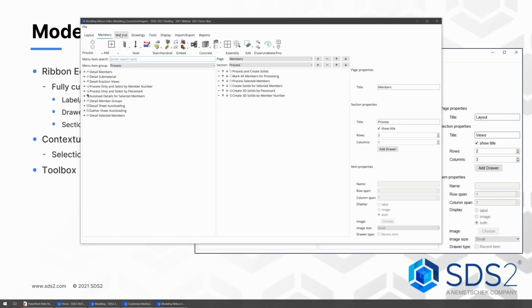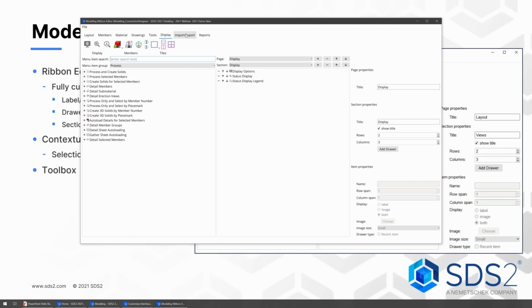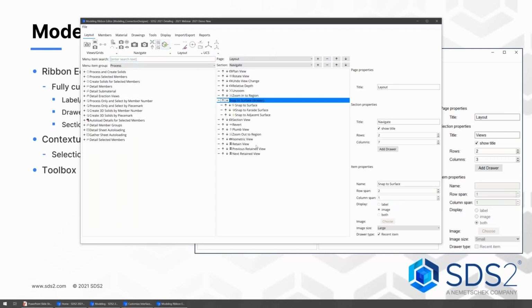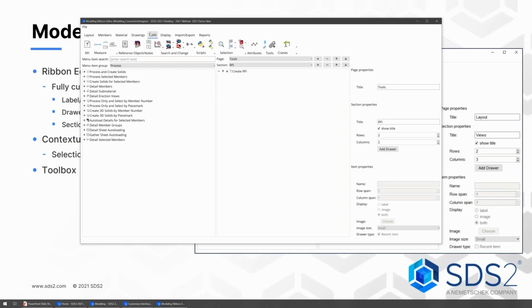And that covers it as far as the customization of this whole screen is concerned. So I want to add something here, Aditya. This is really, really cool, and it is pretty easy to use. Just the other day, I did this because I like to have the anchor bolt tool that adds all the anchor bolts if you select a column rather than just the anchor bolt in the member. And it took me about a minute to figure out how to do it.